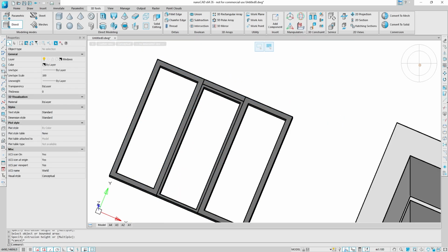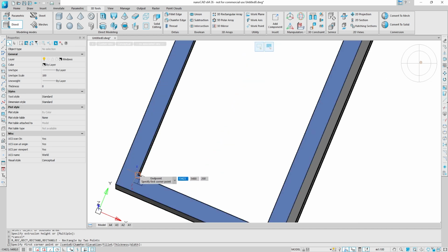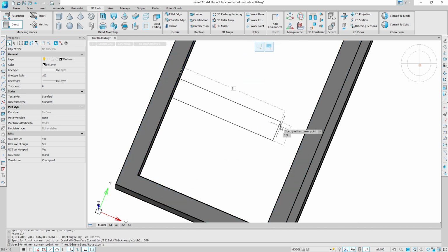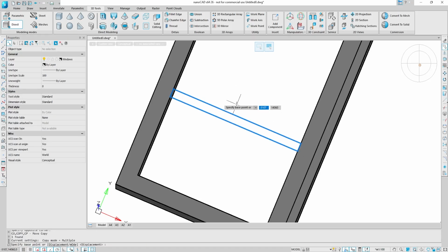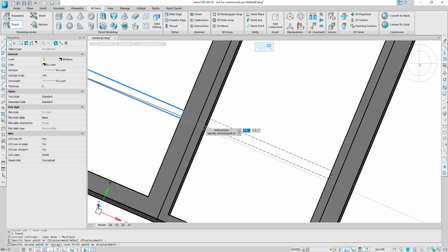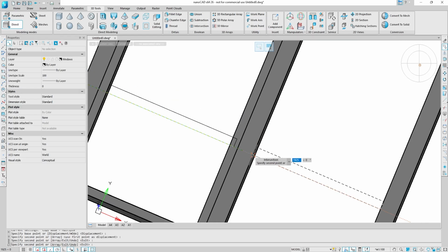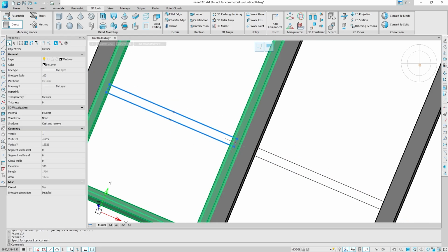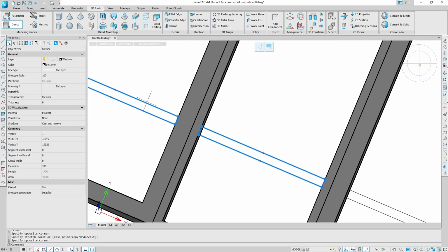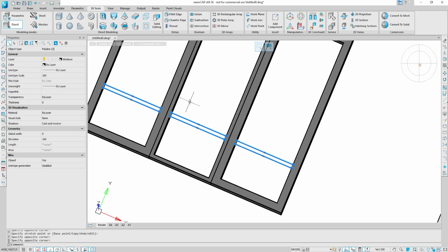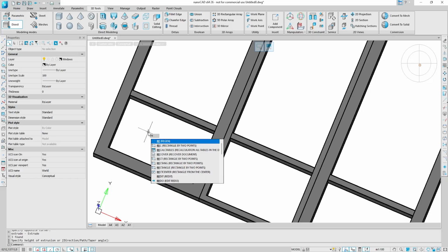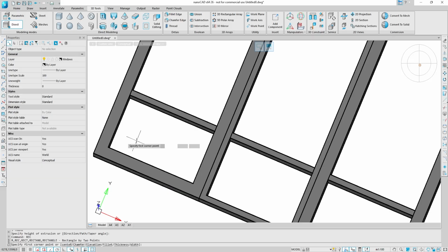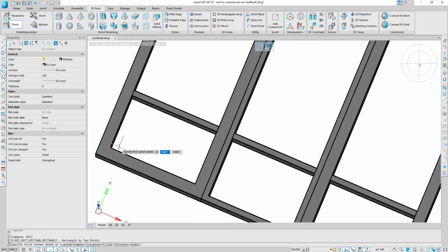Create horizontal imposts in the same way as we did for windows. Length 825, width 50. Extrude the created contours by 100 mm. Draw 6 contours under the glazed units and pull them up at a distance of 5 mm.